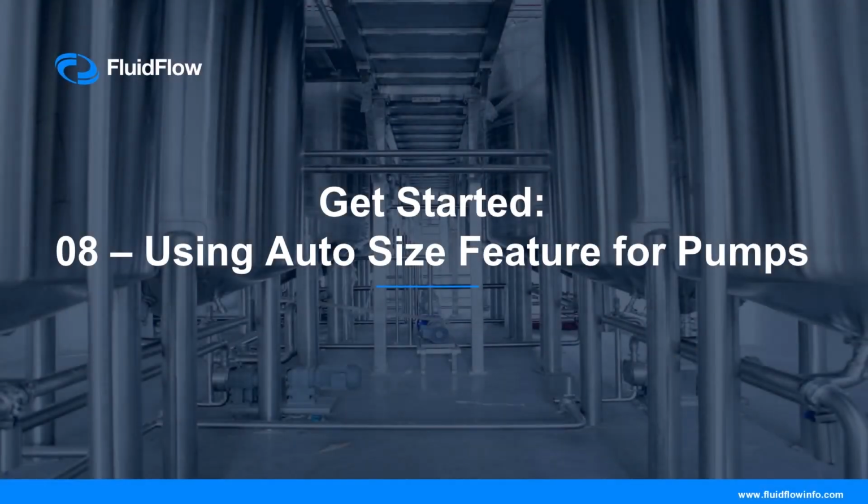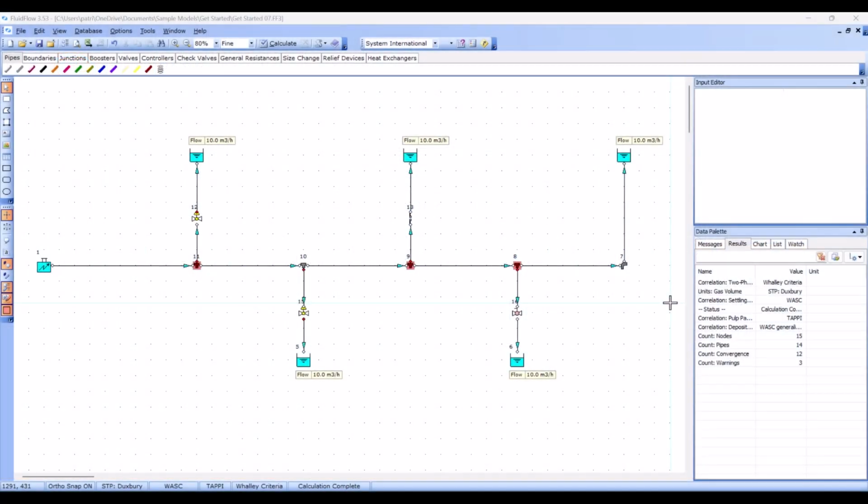Now that we have sized our pipes and achieved the desired flow distribution throughout the system, we can begin the process of sizing a pump. FluidFlow includes an autosize feature for specific components, such as boosters, enabling users to define a controlled flow rate or pressure at a specific point in the system. The software then calculates and provides the information needed to size real-world components, including pumps and control valves.